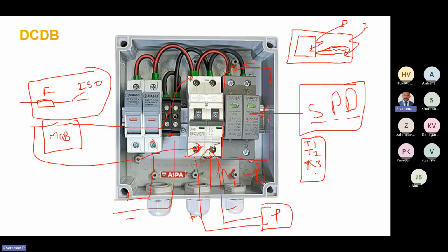For the system where we have a lightning arrestor. Suppose this is the top view, right? Here our panels will be installed on the rooftop. Suppose you have a lightning arrestor like this. In the side view, we have the panel up to this height. This will be a lightning arrestor, LA. If we install this one lightning arrestor, this area will get covered.